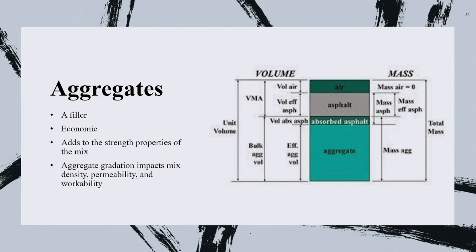Now, when it comes to pavement, we do the same, but think about this. You have the aggregates. I'm talking here about the wearing surface, not the subbase or the base. The subbase or the base, you treat it like soils, more or less. But here, you have aggregates, then you have asphalt, which is 4.5, 5%, and then you have air. But then, remember, on the asphalt, there is something unique, because the binder is different than the hydrated cement. The hydrated cement goes around your aggregates, right? It never penetrates the aggregate.